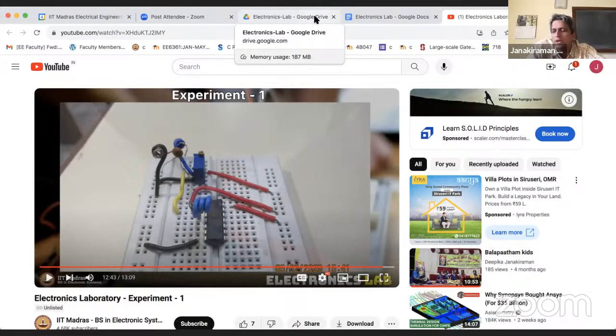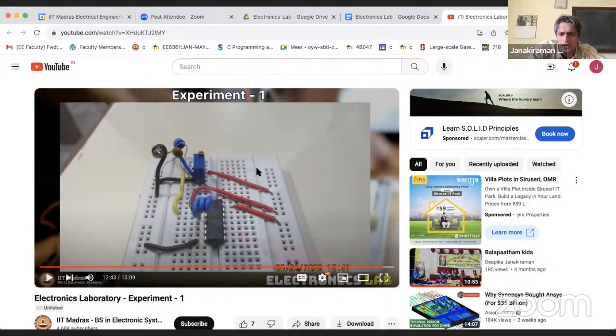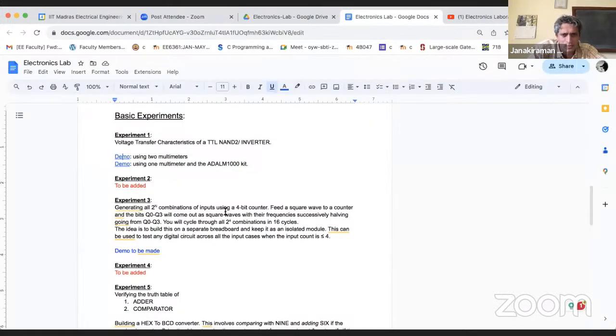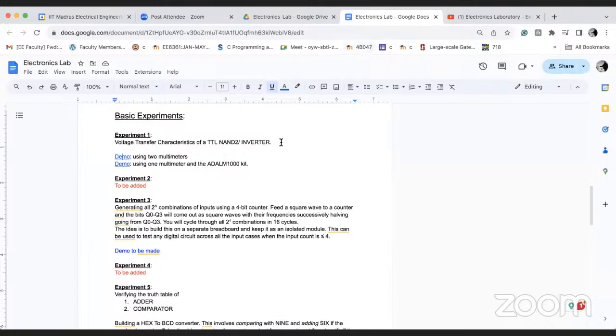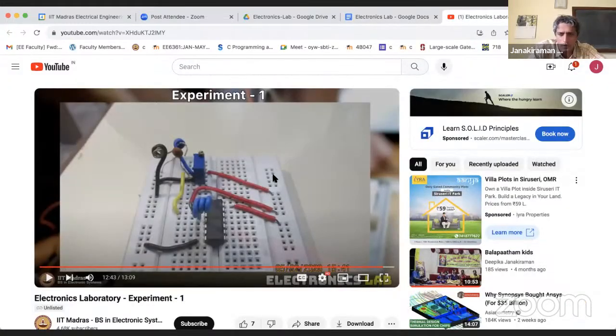But here even if the capacitor is not there, it's okay. Sir, so we can use any value capacitor? Yeah, I have given you some 1 nanofarad capacitor or something. You can put it. Sir, is it a bypass capacitor used to bypass the AC voltage? Yeah, the high frequency noise should just get killed.